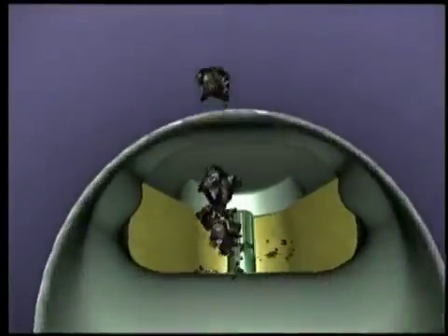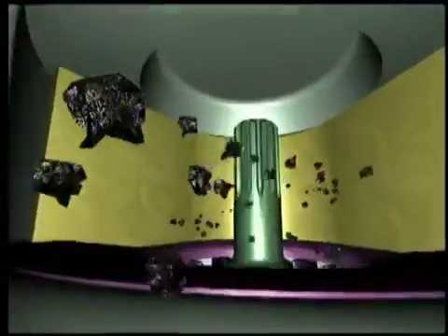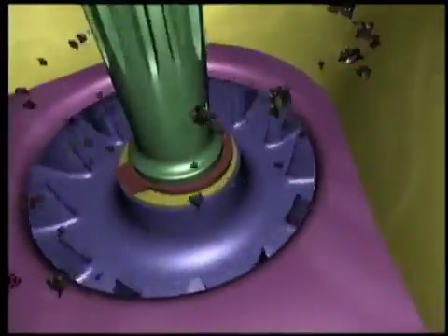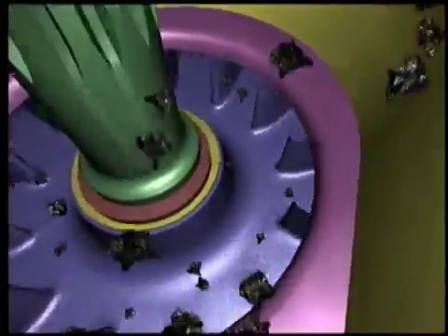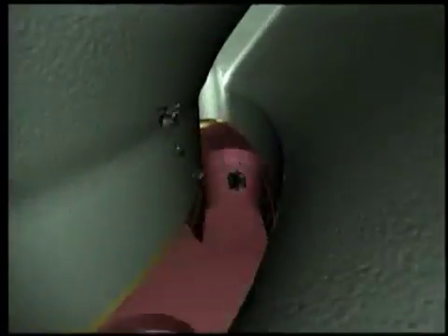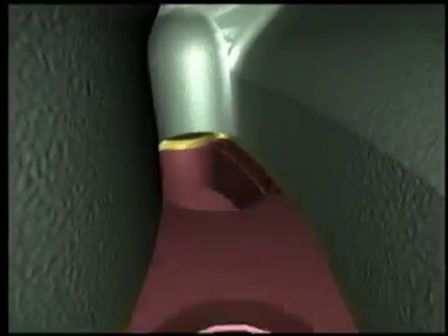Let's follow contaminants in the hydraulic oil as it is drawn from the tank through the hose to the pump. You can see the contaminant's irregular shape with sharp edges and corners. Once the oil and contaminants are drawn into the rotating group of the pump, the contaminants can cause damage in several ways. The larger particles cannot pass through, but will break up as they strike the stationary port plate, shown here in yellow, and accelerate wear.